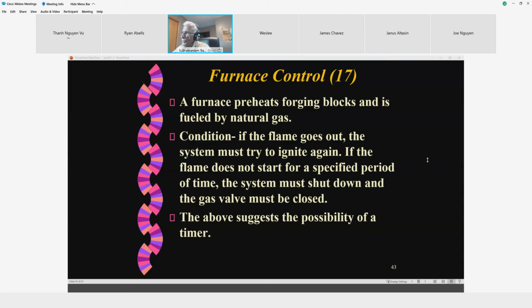The first thing it'll do is to not switch on the fan to the condenser, but switch on only the flame. Now, they all have electronic ignition. So it'll keep sparking to light up the flame, but to light the flame, the gas valve must open. It is never left open inside the furnace. Outside it is left open.